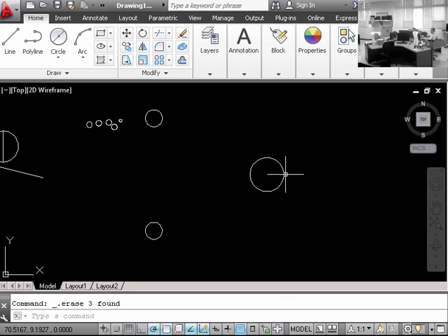Now hole patterns are typically always based on the center of the circles. So those dimensions are pretty crucial, and they like to be repetitive in spacing, especially if you're going into fabrication of heavier steel, those kind of things. Standards always like typical spacing, so keep that in mind. All right, so it's all about the practice, though.